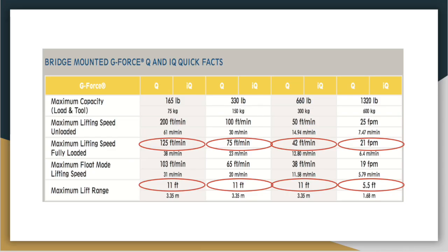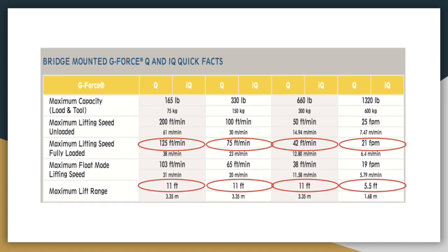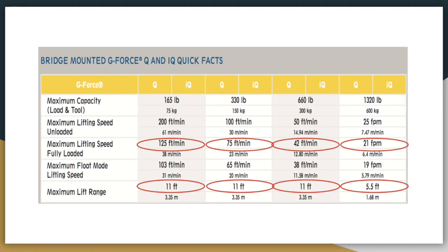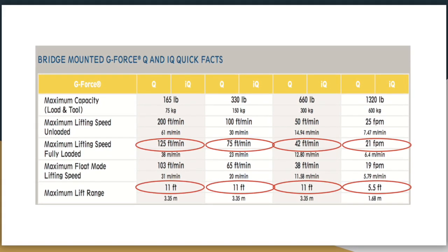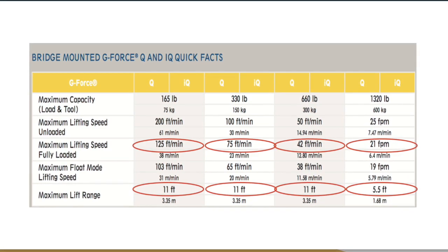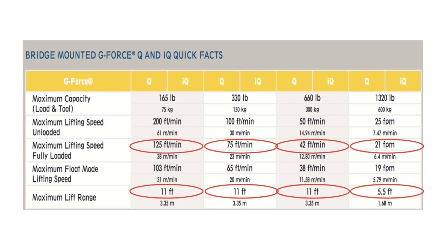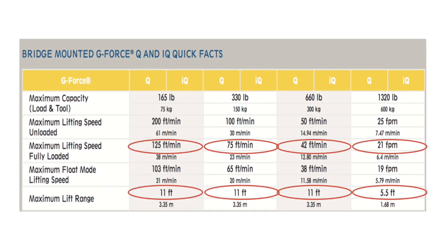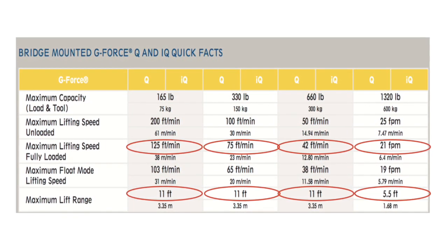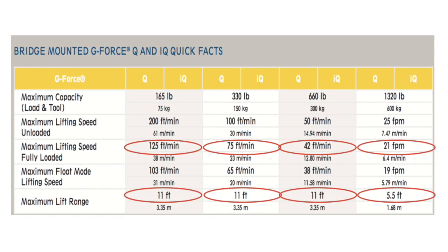We obtained a chart from a Gorbel brochure and were able to determine the maximum lifting speeds when the device is fully loaded. We assumed that it was fully loaded so that we could obtain the maximum force due to acceleration. We also converted it from feet per minute to feet per second. And we found the maximum lifting range of each size G-Force.